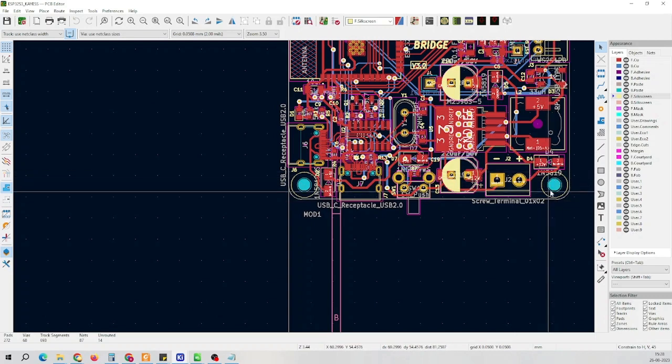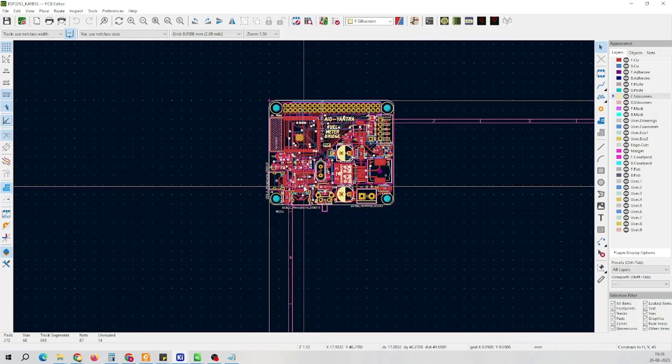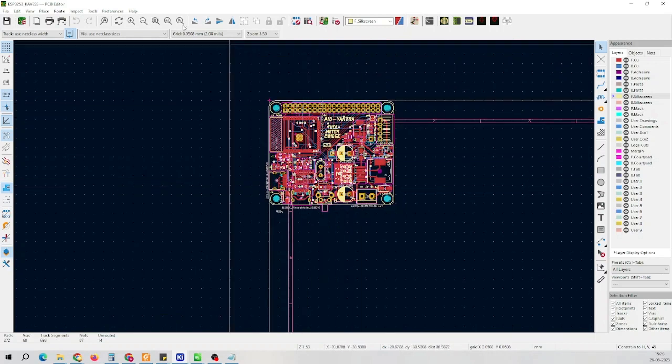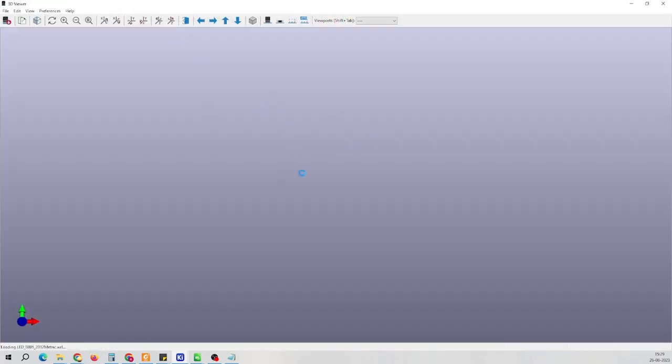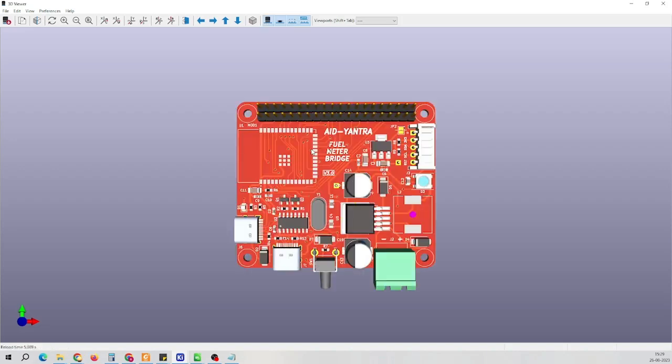So these holes are basically given so that the PCB can be placed at some higher ground by using some nuts and bolts. So by using some nuts and bolts on these holes, we can increase the height of the PCB so that the bottom side of the PCB does not touch the bare side of the board.